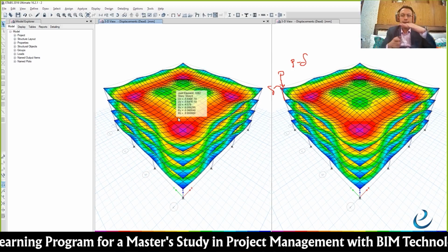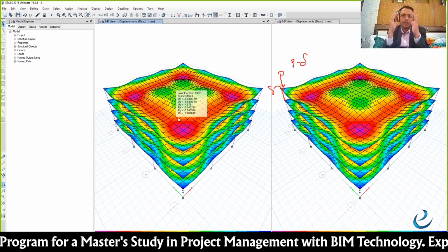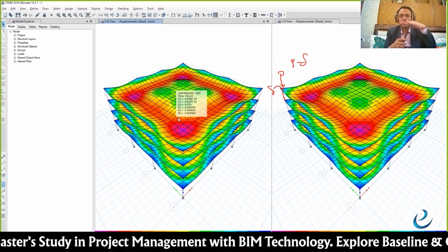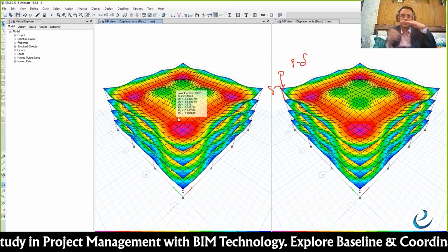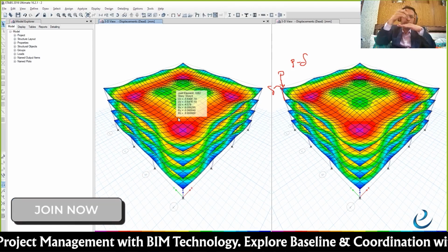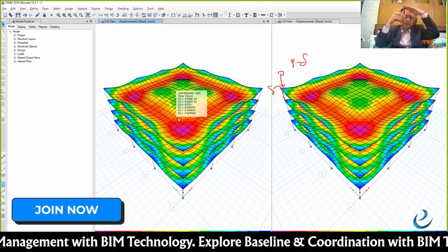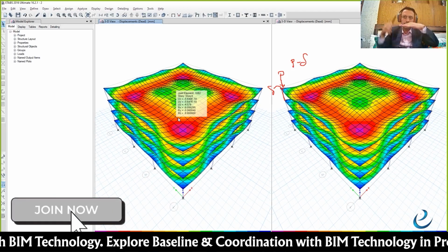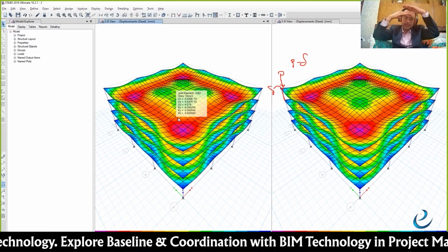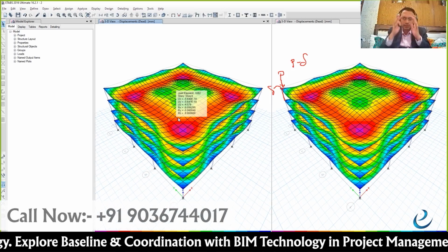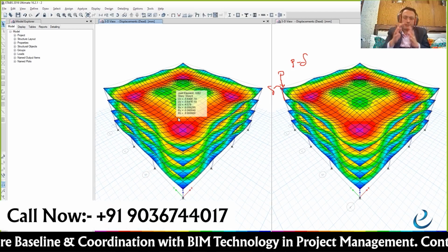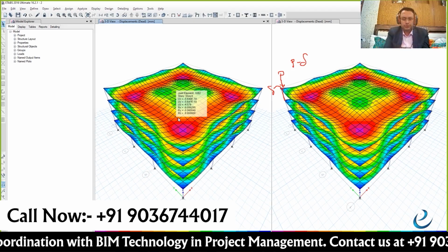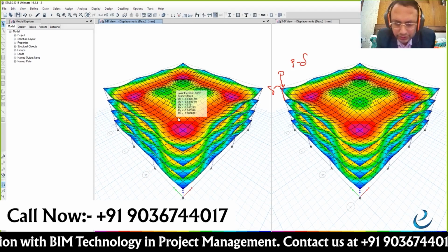See, every floor, the entire building, you cannot construct at one go. Am I right? So what you will do is one floor with the columns here. You will add the columns above the slab. You'll put one more slab above this. Like that, you will go on casting one slab, then the second slab, then the third slab, and that's how the cumulative effect on the columns and beams comes. Not in one go. That is what the construction sequence analysis actually is.